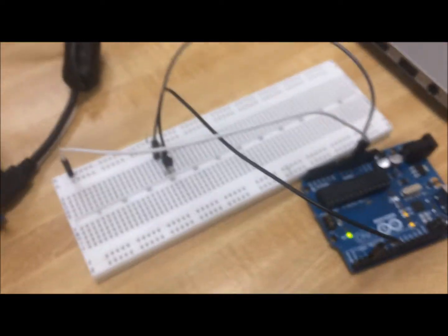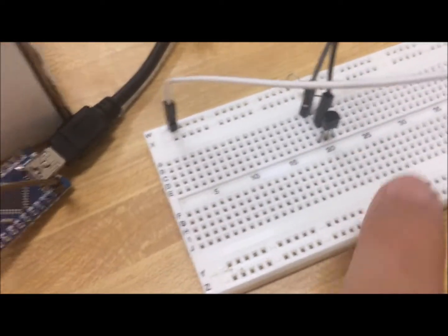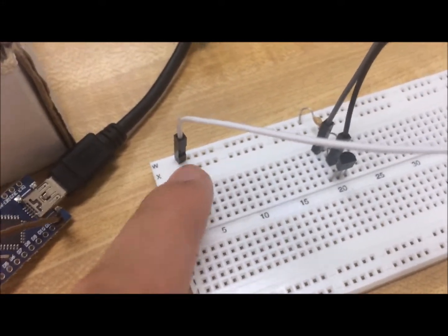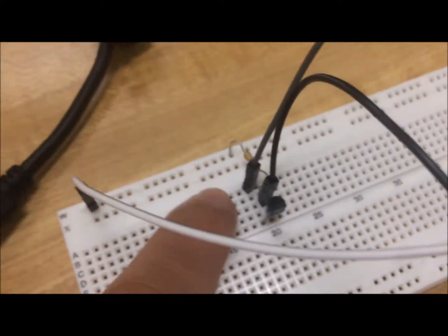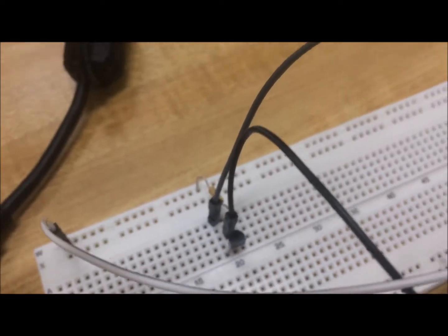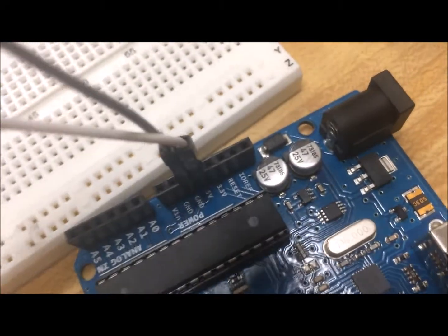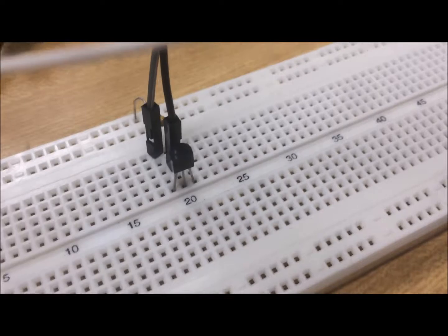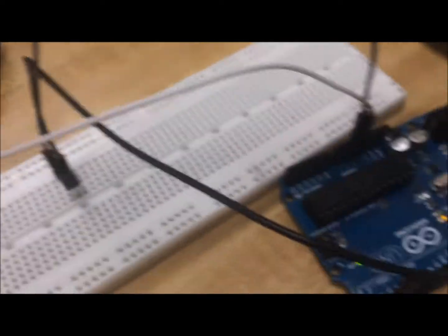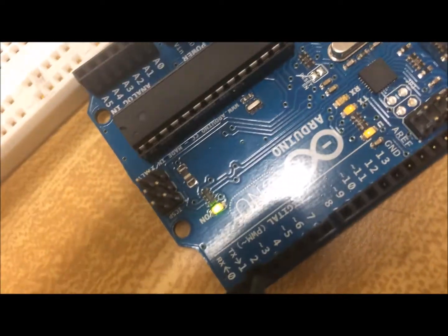If we go to the setup that we made with the Arduino Uno of the temperature sensor, you can see that right here is the voltage supply, and if you follow the wire, it goes to the 5 volt pin. Over here is the ground port, and if you follow that wire, it goes right next to the 5 volts to the ground port. And the last port is the data in and out. If you follow that, it goes all the way to pin number 2.